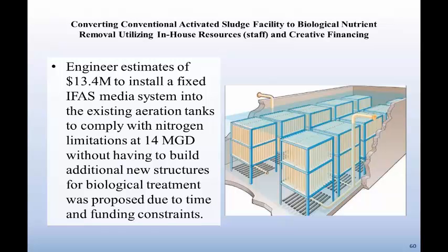In addition to that, there was also discussion with the regional board, who were concerned about our solids dewatering facilities since we are using drying beds. They were concerned that nitrates or ammonia was bleeding into the groundwater table. And actually they were calling to potentially force us to build mechanical dewatering facilities. And this would have added additional challenges due to the high ammonia side stream that we would have to take back to the plant, so that would have impacted our capacity even further.